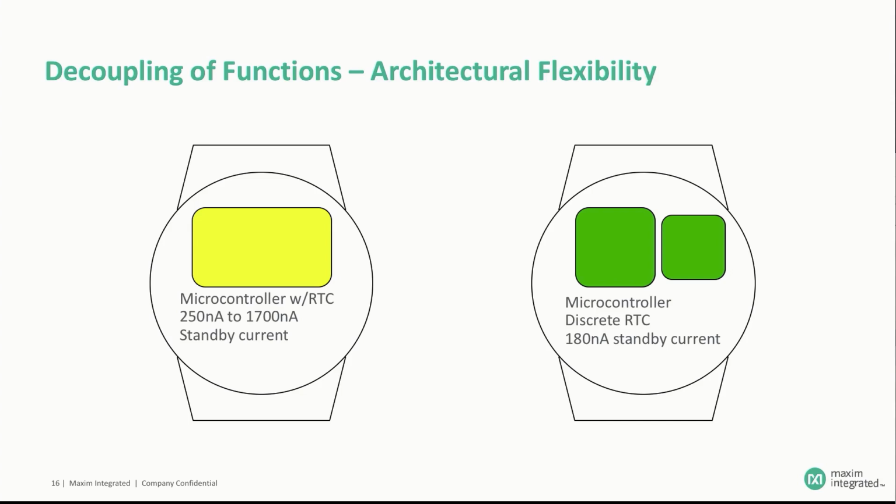Another example is power management ICs, or PMICs. PMICs became extremely popular during the advent of digital cameras, and especially smartphones. They contain a big switching power supply, maybe more than one. They also have a bunch of LDOs, GPIOs, maybe a battery charger and/or a fuel gauge.